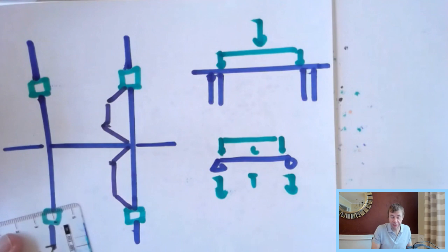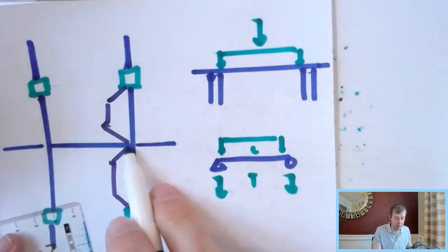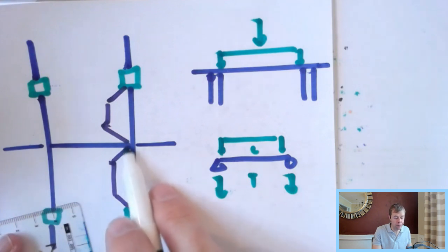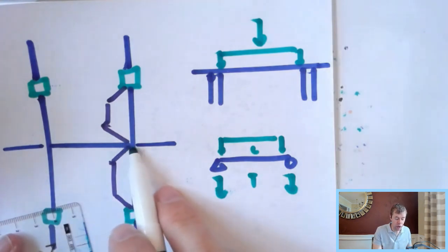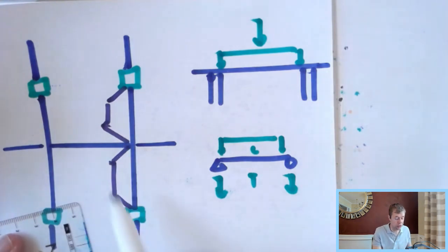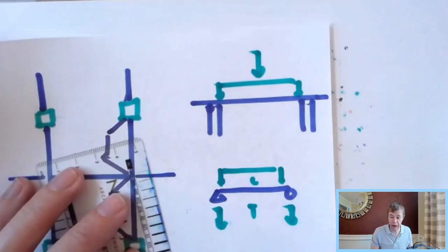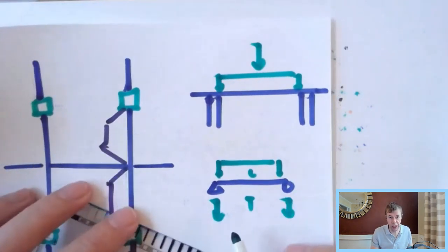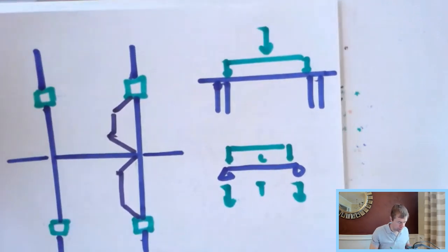So that's a fine way to do it. If you designed it in this system, you might expect a little bit of cracking right here in your slab. You could put a little bit of tension steel up there if you wanted to, temperature and shrinkage steel up there, to try to keep that crack small. But that, Rihanna, I hope answers your question. If not, then ask me some more in the chat. So yeah, there you go.